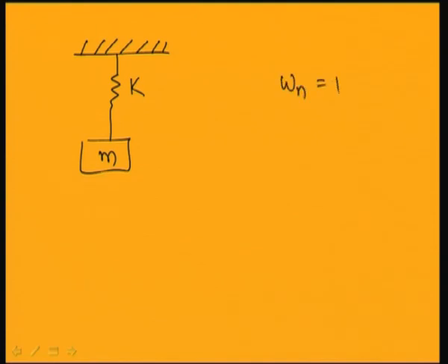So, let us take some examples. As a first example, let us take a discrete system in which we want to find the eigenvalue. For example, let us first take this simple system with k and m. In this case you already know the natural frequency of the system is equal to root over k by m. The same thing you can find using this Rayleigh method.